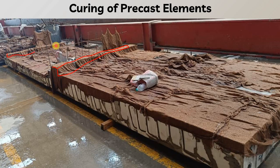Here also we have the nib, and these are the U-bars that are placed in position to connect with the other precast wall panel. And below you can see these are the dowel tubes that are placed in position to receive the dowel bar from the panel below. So this kind of gunny bag is used for curing of the precast element.